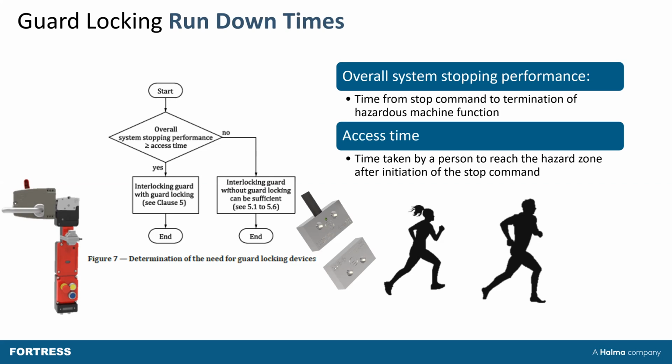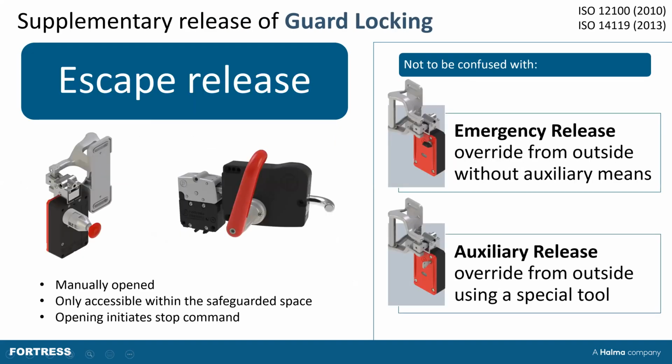You might want guard locking, but the only reason you need it for safety is if you can reach the hazard. If you're able to reach it while it's still hazardous, then you're going to need some kind of guard locking. And if you have guard locking, remember that's locking the gate shut, not some kind of non-contact arrangement where you can actually open the gate any time. It is locked shut. That then brings up some other issues. You may also need some way of releasing that guard locking in an emergency.